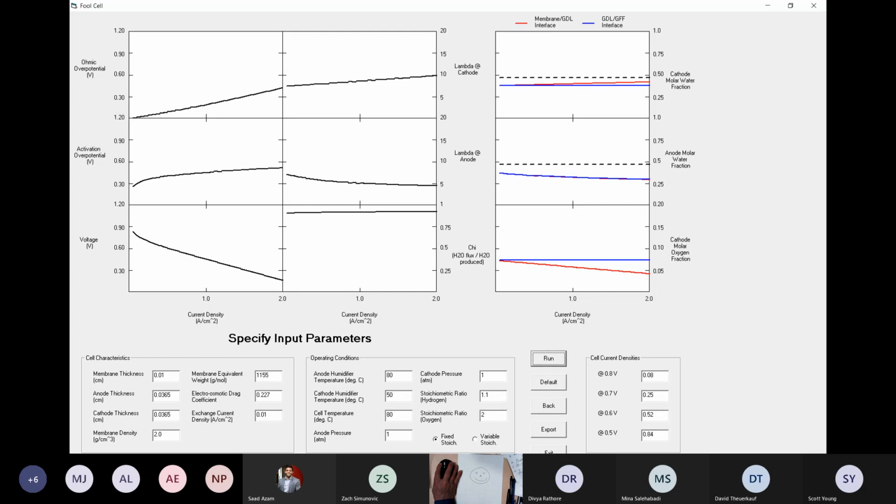With respect to the hydrogen side, you just don't want to waste hydrogen. So running the stoichiometric ratio on the hydrogen as close to 1 as you can is the best thing to do. And when you're running fixed stoichiometry, it means every time you change the current density, you're changing the gas flow rate to match what's required. So it's tricky, right? It's a fairly tricky operation. Running the cell at a fixed current density is far preferred than going back and forth, up and down like crazy.